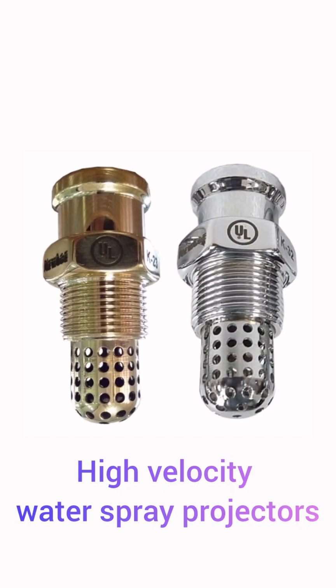The other pipeline will be filled with compressed air at 3 bar pressure. The network pipeline diameter will be 25 mm. The conical spray of water is discharged through specially designed high velocity projectors. This is the picture of the projectors.